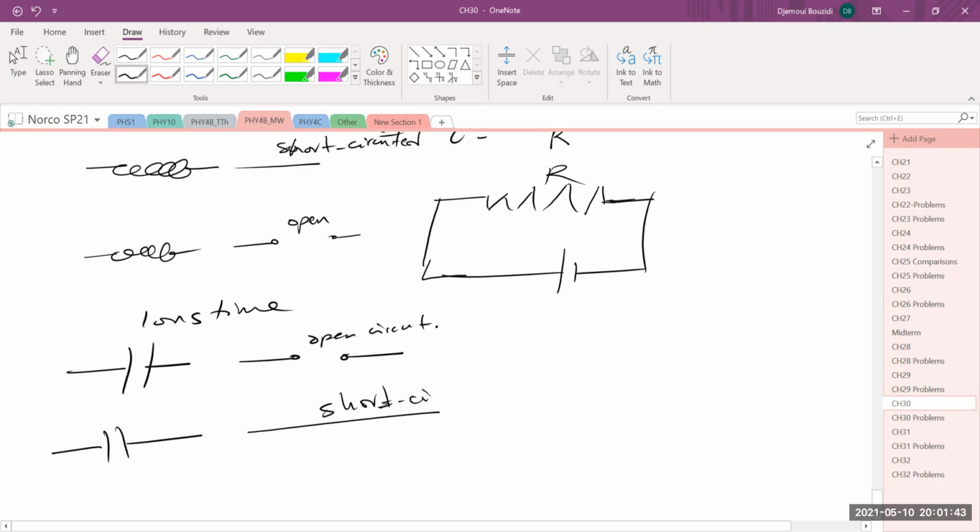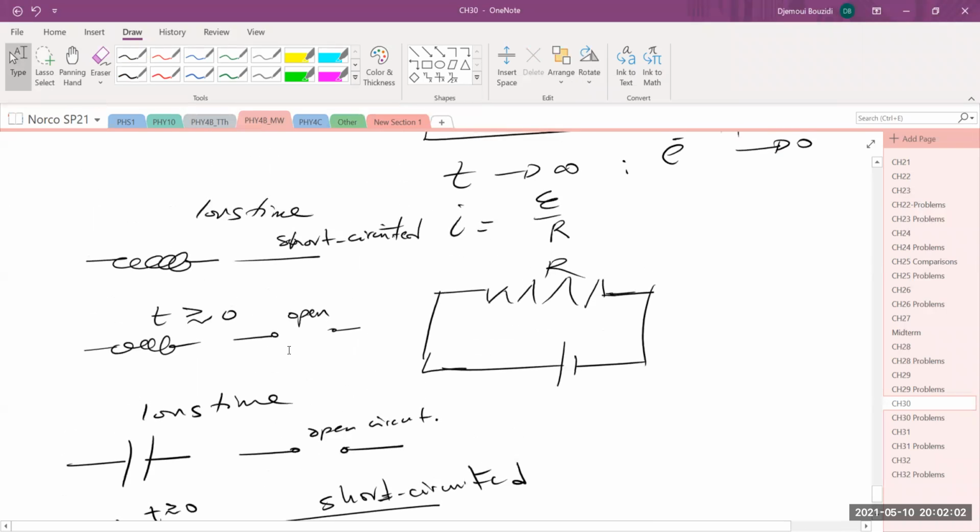So everything looks opposite to everything in here. Okay, so this is immediately around t equal to 0, greater than 0, but immediately next to it. And so this one is actually greater than, but very close from 0. The inductor behaves like an open circuit. It's going to open. So whenever you see it, just make sure no current is running through it.